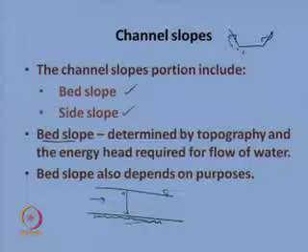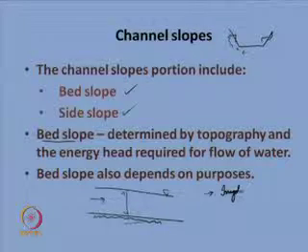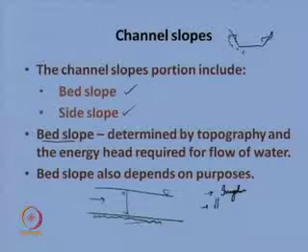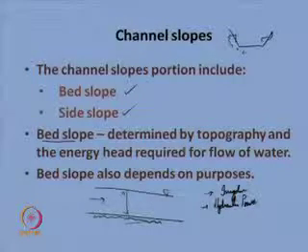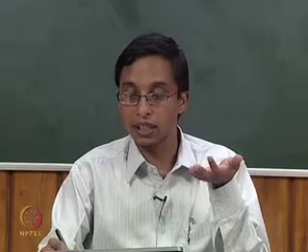The bed slope also depends on various purposes. Say for example, if there are multiple irrigation projects or hydraulic power projects, you will see that the water at the entry of the channels for irrigation purpose as well as hydraulic power projects should be at quite a higher elevation.